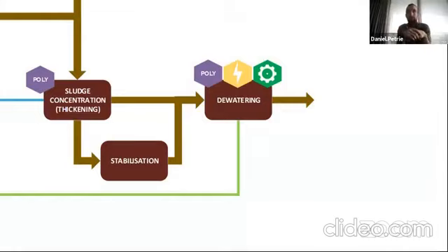You might need machinery and energy to apply quite strong shear forces to the sludge or the digestate, and those shear forces are able to disrupt the structure of some of those particles in the digestate or sludge, and that allows you to remove more water. So these all have to work nicely together: the chemicals, the machinery, and the energy that you apply to it to get a really nice thick solid.